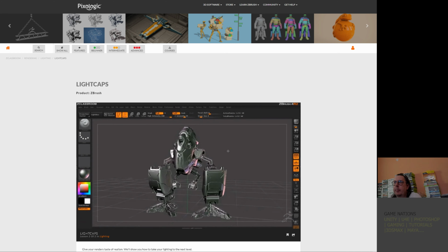Of course, I can adjust the falloff and the aperture and the strength of each light individually, and you can create some interesting effects. So I have an aperture of about 60 on this light, and I've lowered the falloff, and this creates kind of a hard edge to the light, which results in something that looks kind of graphic or hand drawn. It's a very cool effect.